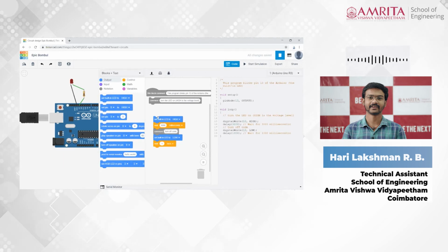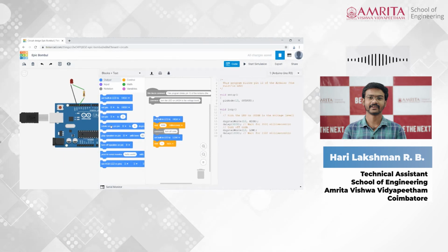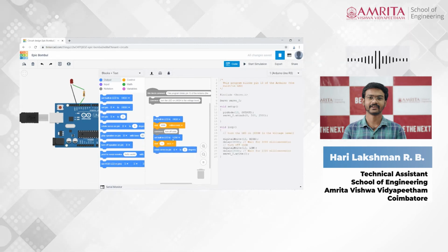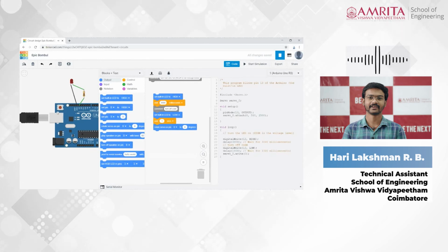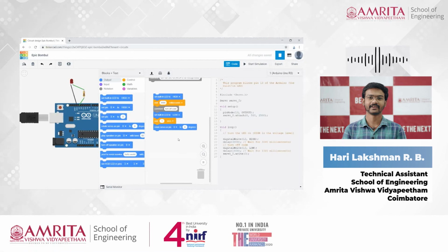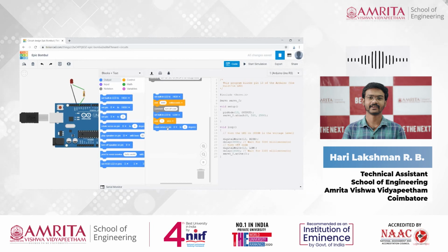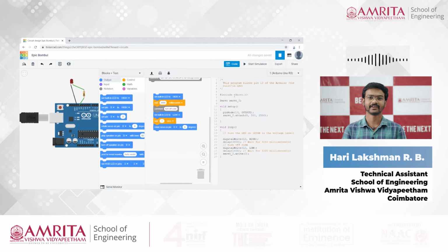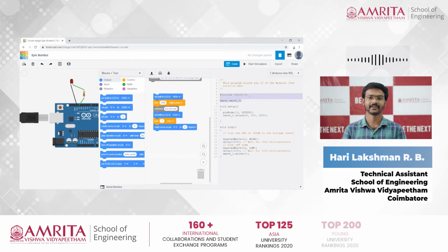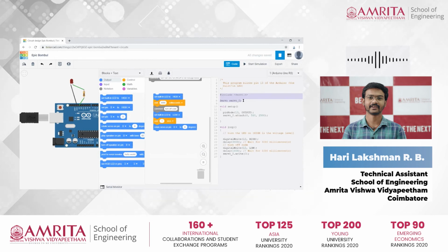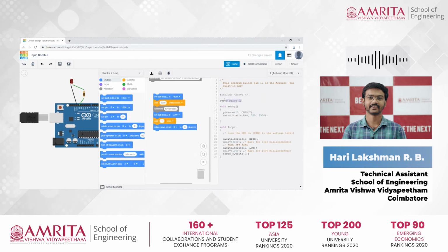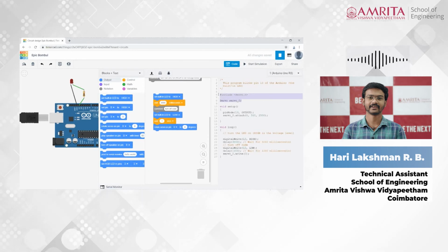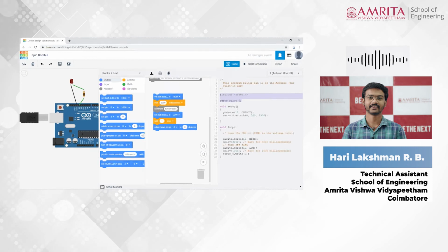And as I said earlier, you can also add more functions. Before moving on, I'll just show you about it also. I have just assumed that I'm having a servo attached to the Arduino. So when I attach this code over here, a new function or new code has popped up here. This is called a hash include servo and servo underscore zero. It means that it automatically adds the necessary package that would be needed for this Arduino program.